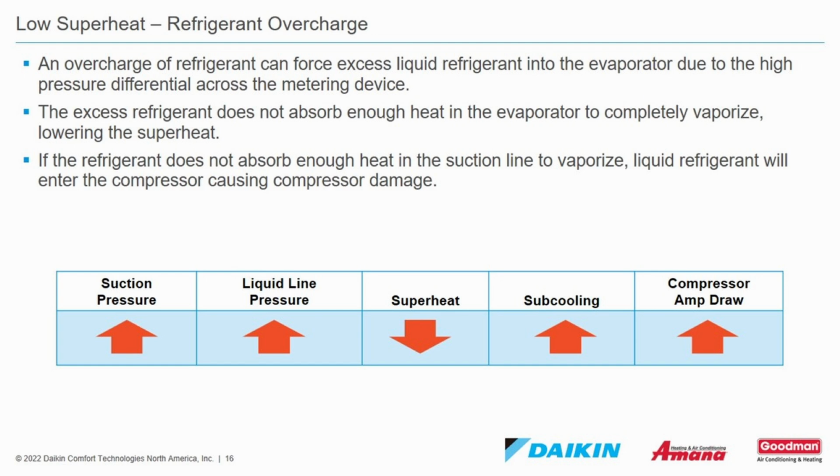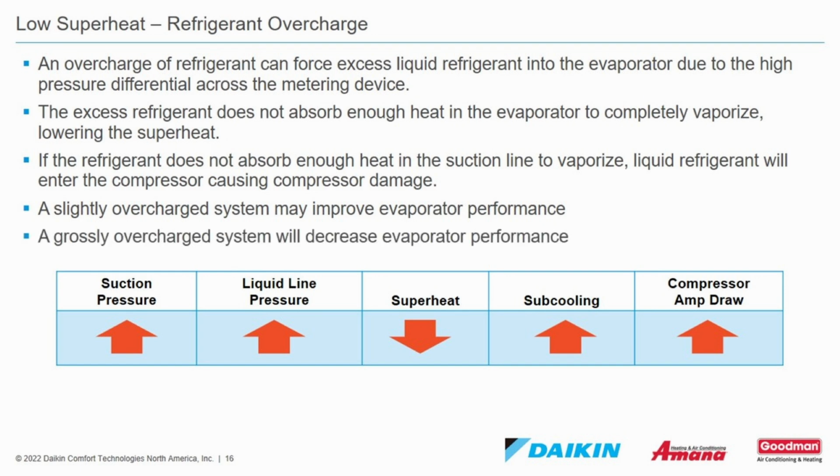If the refrigerant does not absorb enough heat in the suction line to vaporize, liquid refrigerant will enter the compressor, causing compressor damage. A slightly overcharged system may improve evaporator performance. A grossly overcharged system will decrease evaporator performance.